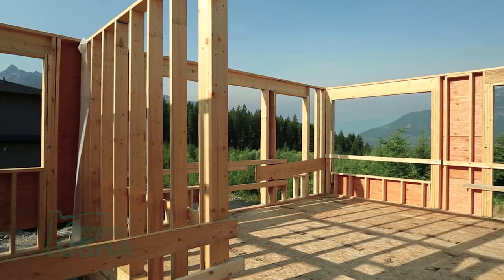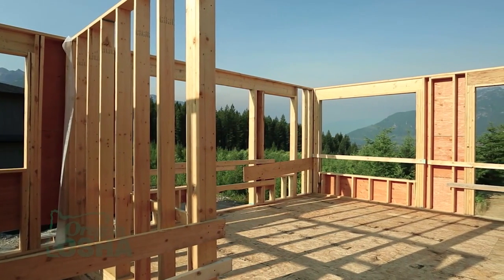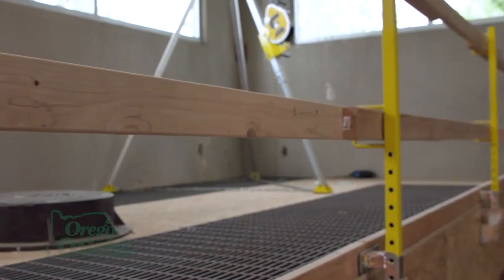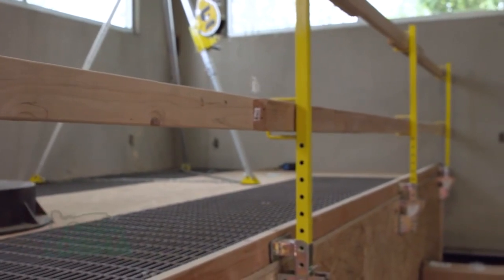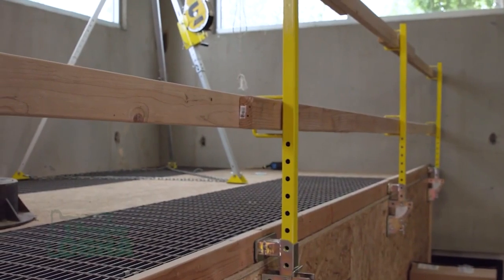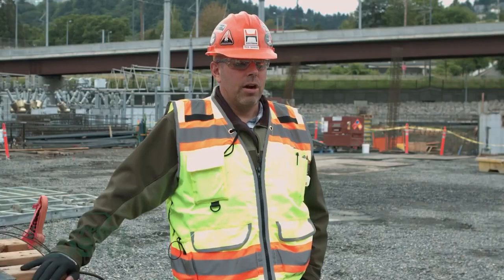The place that I've seen most innovation when it comes to guardrail systems is framers that are putting these guardrails on the walls before they're stood. So by the time the wall's vertical, it already has a guardrail for the next level. Something else that I've seen with the guardrail systems is they have these prefab sockets that you can basically bolt to the side of the structure. It's a little bit faster, it uses less material, and I've seen some larger outfits use this, especially on large commercial projects. How effective are guardrails?